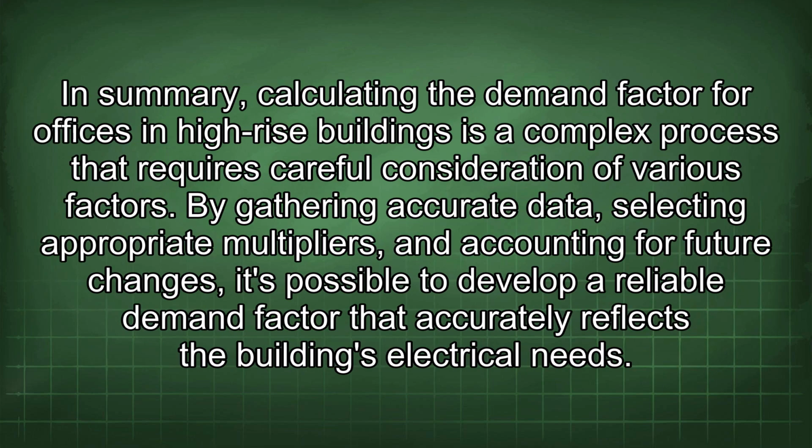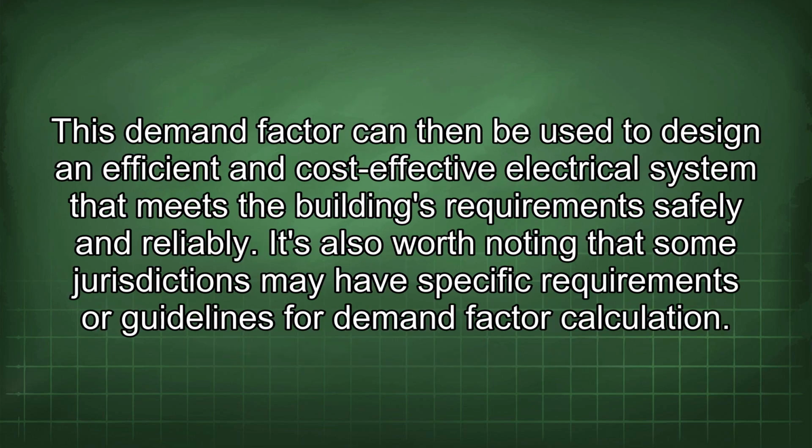In summary, calculating the demand factor for offices in high-rise buildings is a complex process that requires careful consideration of various factors. By gathering accurate data, selecting appropriate multipliers, and accounting for future changes, it's possible to develop a reliable demand factor that accurately reflects the building's electrical needs. This demand factor can then be used to design an efficient and cost-effective electrical system that meets the building's requirements safely and reliably. It's also worth noting that some jurisdictions may have specific requirements or guidelines for demand factor calculation.